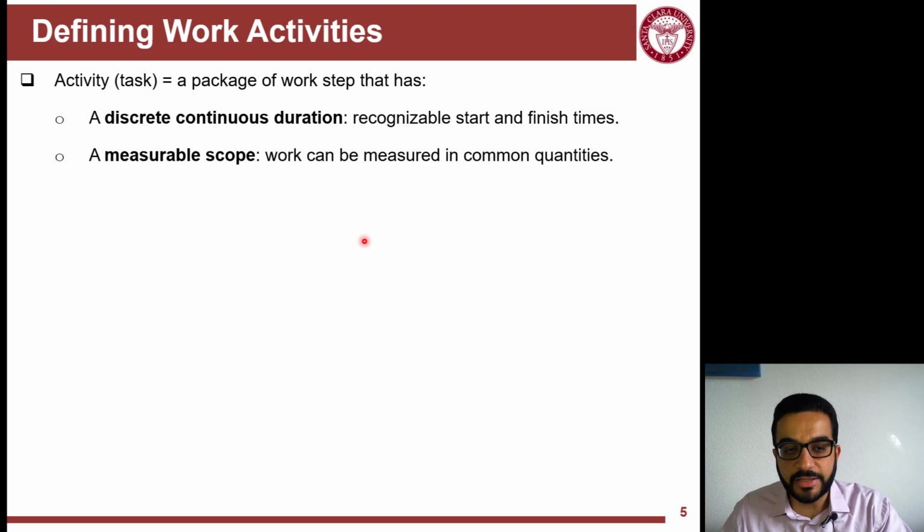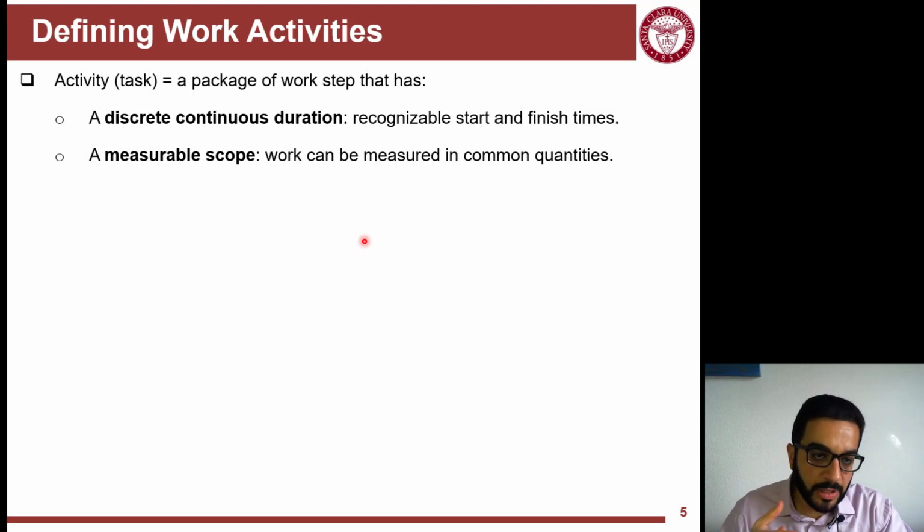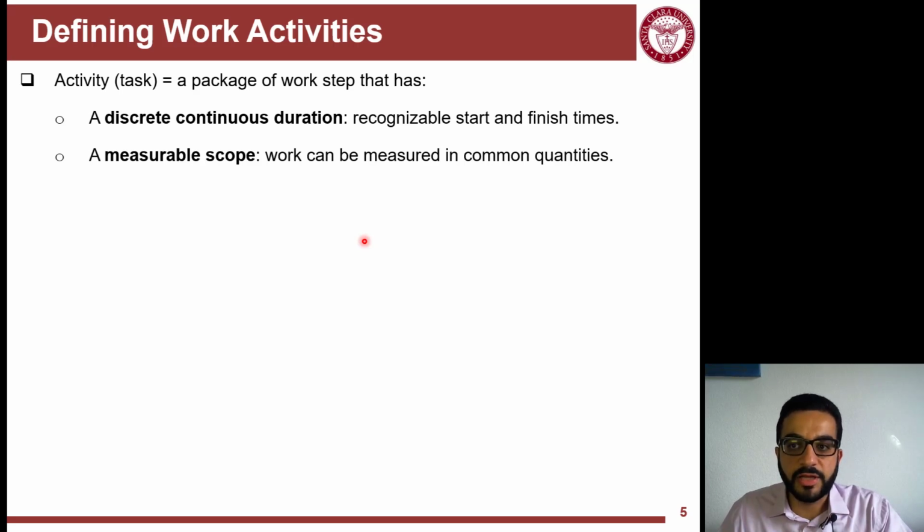Because this classroom will entail stud walls, plywood, mudding, painting, and every one of these has its own quantity of work. So you have to have the activity measurable in a quantity that's simple to track and can be used to track the performance of the activity. But just saying I will finish this classroom is not up to the level of detail of quantities that you would like to track and control your progress and performance.